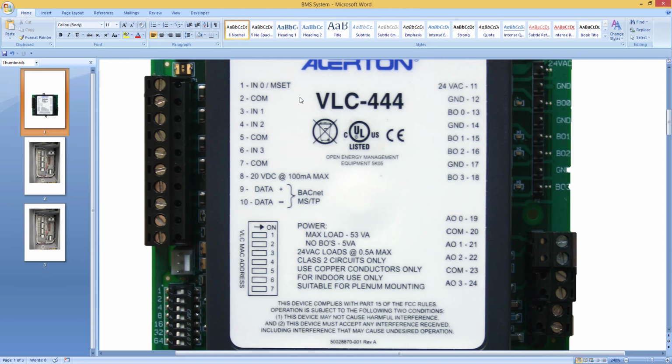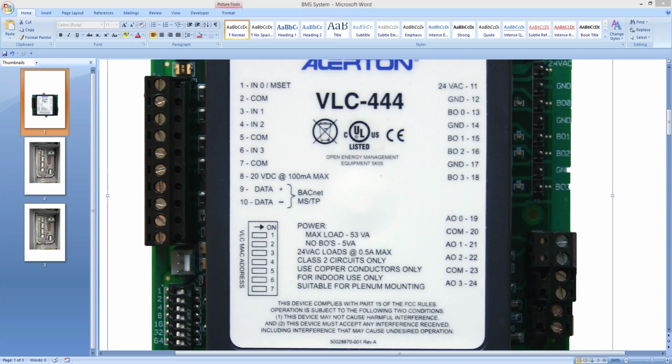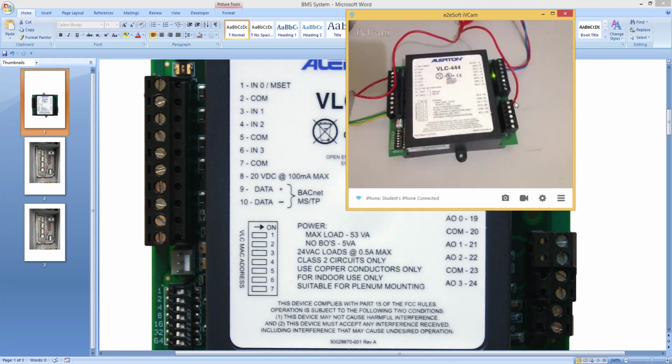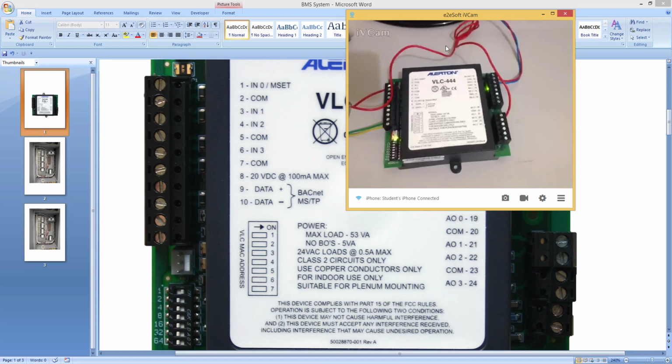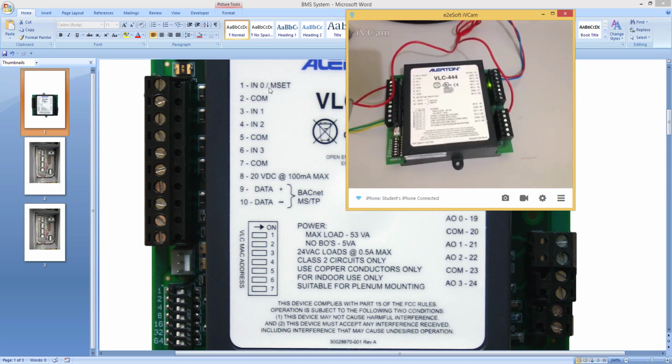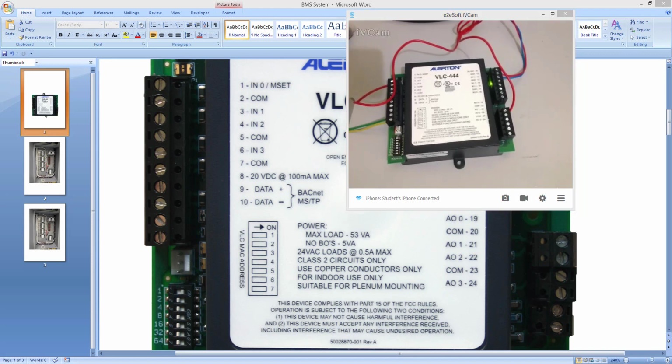And now let's see analog input connection. For that purpose, at pin number 19, I'm going to connect one wire from analog output to pin number 1 analog input. Why? Because pin number 1 analog input is configured 0 to 10 volt. So I'm going to write on that output, and I will connect back into an analog input. As you can see the wiring here, from this pin I take this wire and this is connected to the in one.